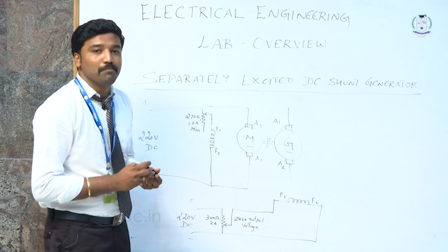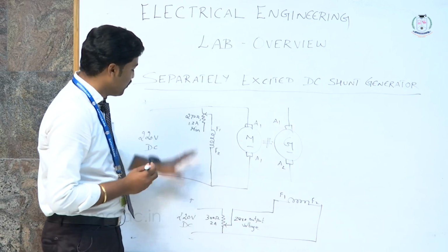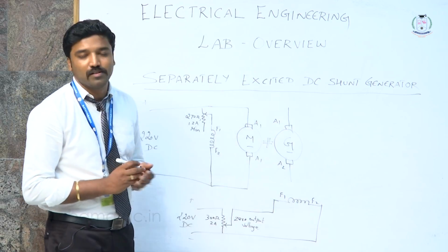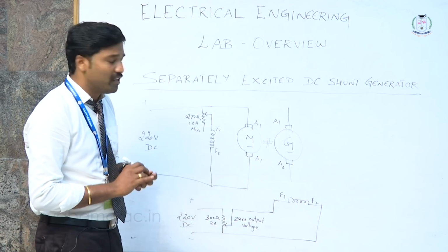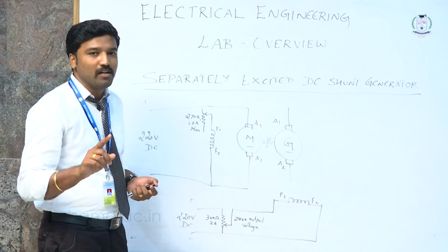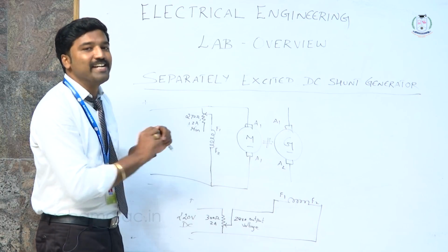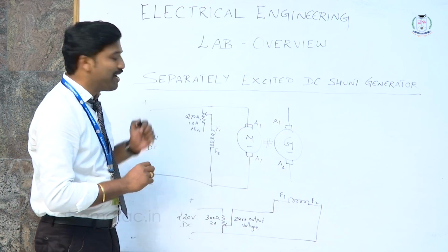So its connection resembles the zero output voltage rheostat. Okay, so two rheostats we have made, two fields are ready, the motor is ready, the generator is ready, everything is ready. Let me complete the experiment by means of the additional terms. As we know, any motor, that too a DC motor, needs a necessary starter. I am going to add a starter.